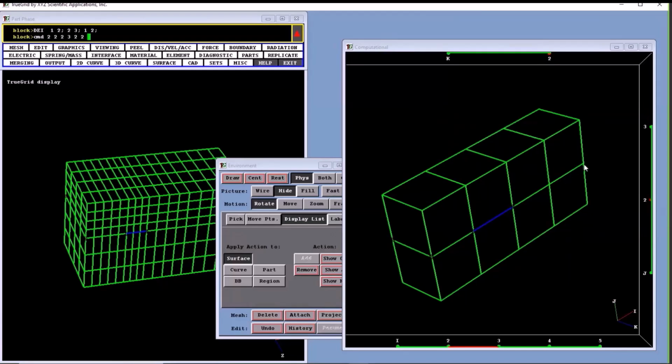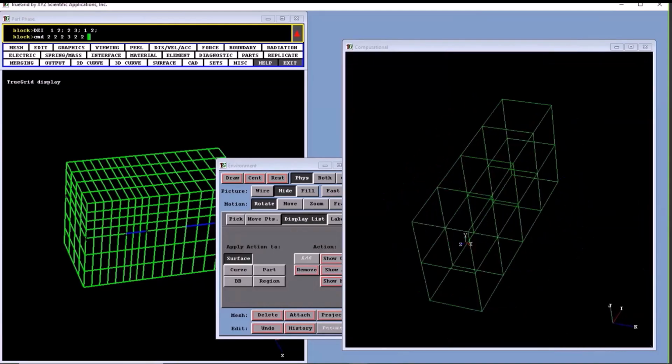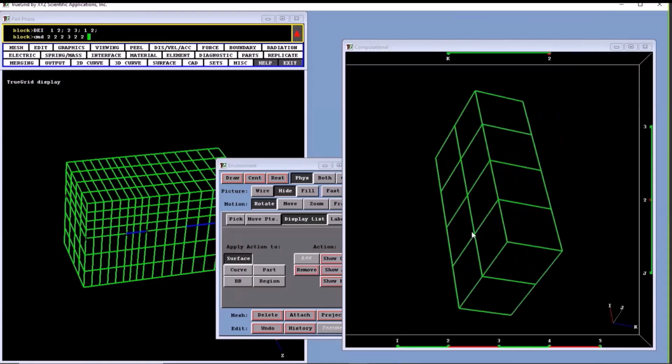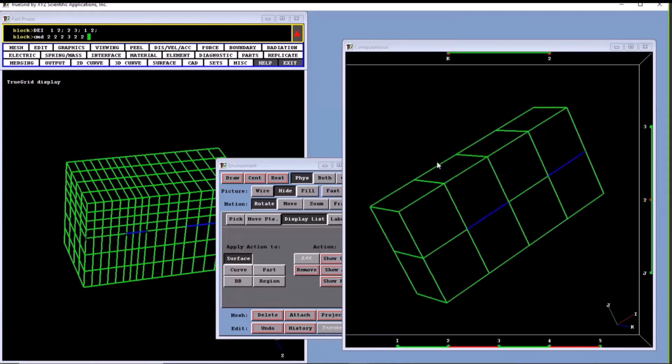Well, this is in the I direction, and it's the maximum edge, maximum I interval from 4 to 5. So what I do is I do a click and drag to make the selection, the interval between 4 and 5. Suppose I want not only these 2 edges, but these 2 as well. I just click on K. Notice that I'm able to select nodes multiple times in the K direction, and I suppose we could do it in the J direction as well. But I can only select intervals in the 3rd direction, in this case in the I direction.